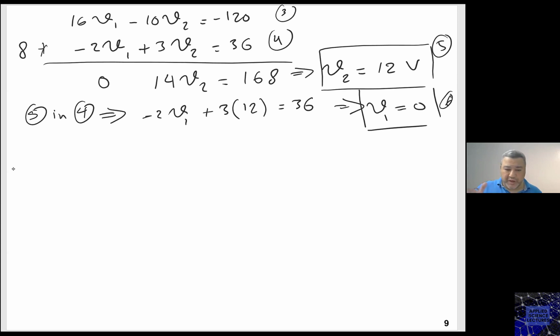But we have shown you that if you go the conventional way, which is putting the currents first on the circuit, writing KCL, and substituting those currents with their equivalent expressions, you would get at the end exactly the same results as the inspection.